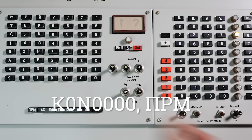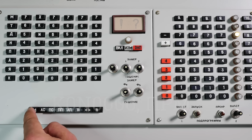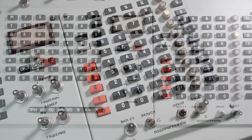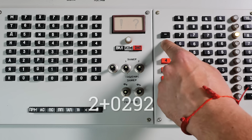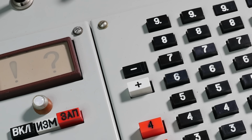So I type here K0N 4 zeros, the power of all channels. Then I press parameter and here I need to enter plus 2.92. But how do I do this on this keyboard if it doesn't have a decimal separator? You do it this way: you enter here 0 to 92 and then I press here 2, which means a magnitude, basically the position of the point. And then, using the sign plus or minus, I define the comparison. Here I want to see greater or equal to 2.92, so I press plus.